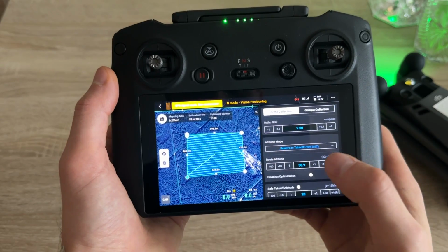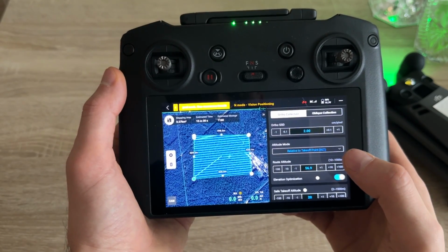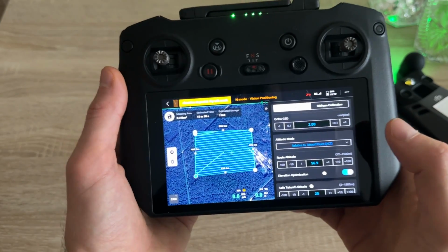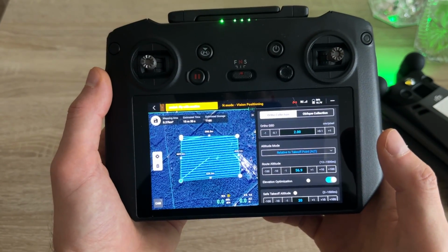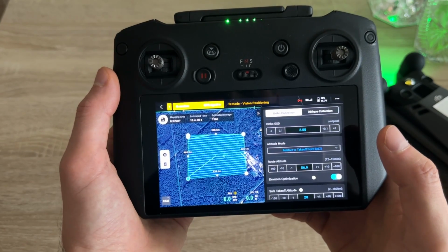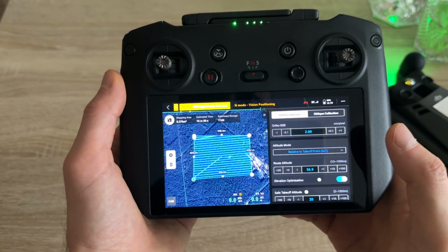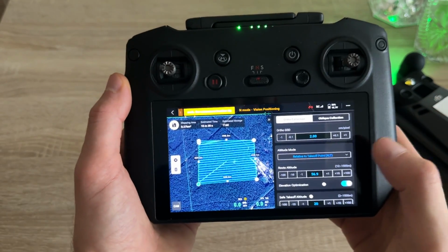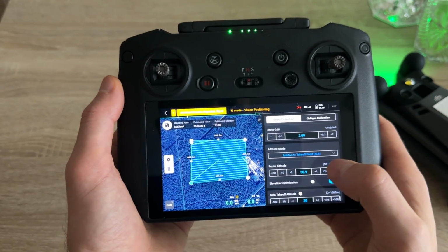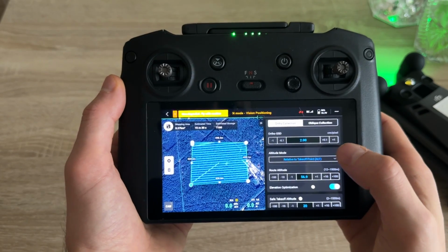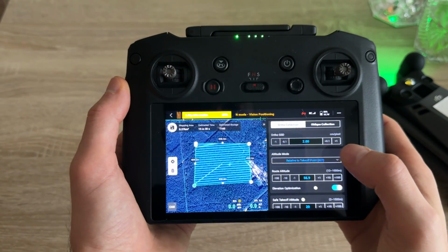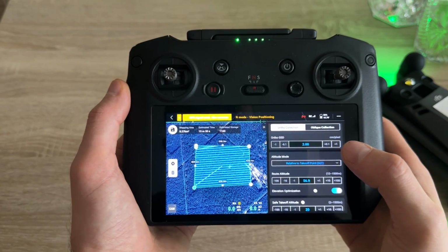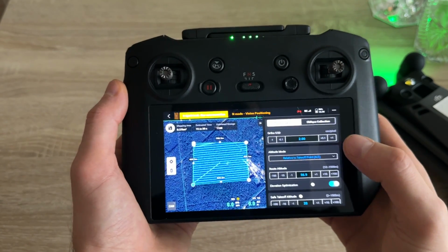So if I compare it to Mavic 2 Pro, 2 centimeters can be available at, I think, 90 meters above sea level. Usually I flew between 70 to 90 meters to get my results. But okay, good thing is that the speed of mapping is much higher than Mavic 2 drone, and that was the thing which I was afraid of at start.